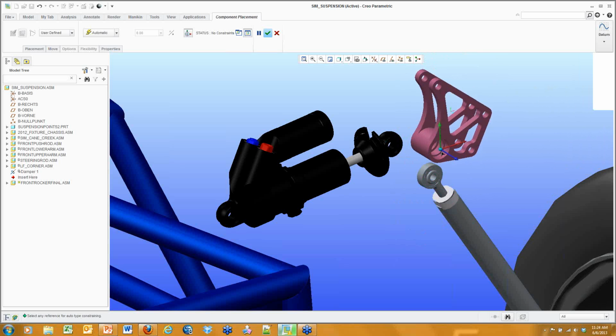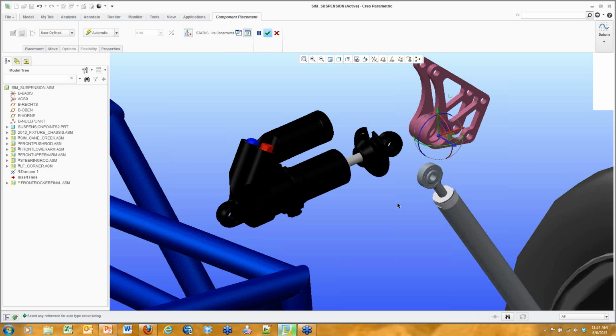All right. So what we're going to want to do is align this larger hole here with an axis. There is going to be a bracket here, but because this thing was built using master modeling techniques, we're simply going to use the skeleton to set this thing up. So we turn on my axis as well as my point display, and I'm going to use a pin connection.